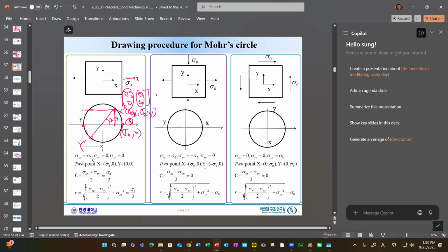Well, you don't have to use this Mohr circle, but it gives us real insight into the transformation of the stresses. As you can see, no matter how much we rotate, the maximum possible tension load is here. Minimum possible normal stress is here. Maximum possible shear stress will be here and here, right? What does it mean?